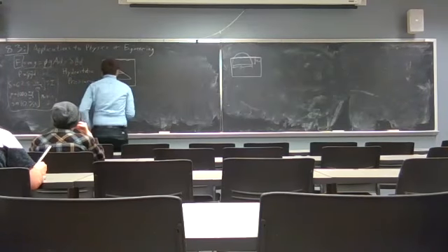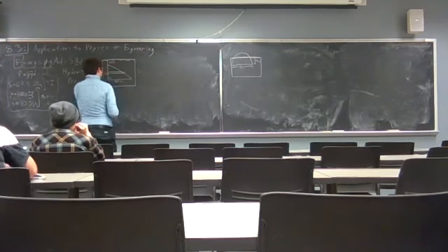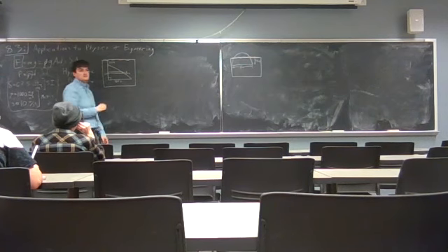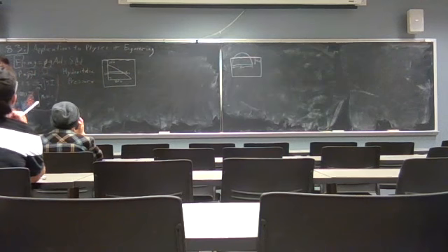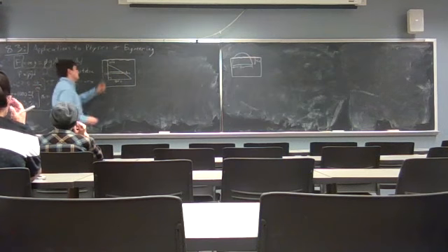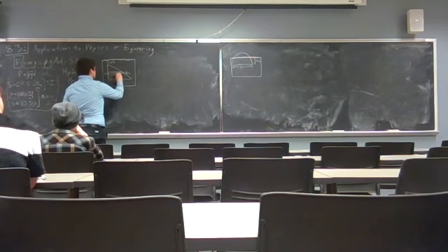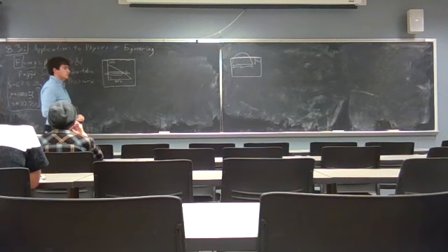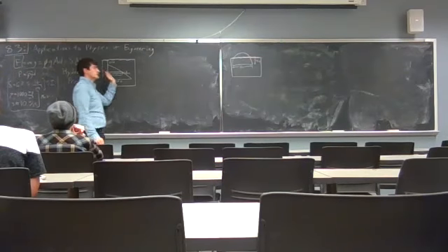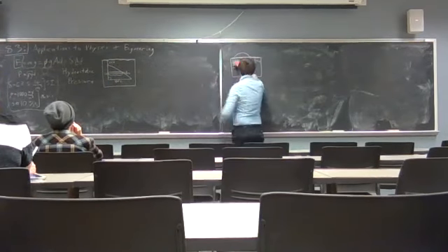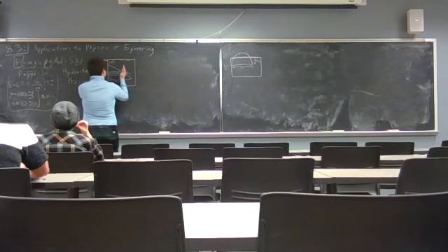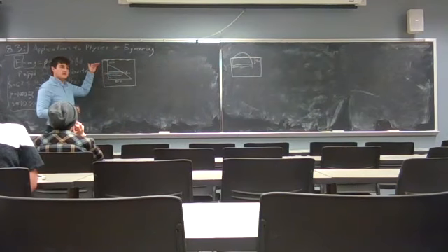When we add up all of these rectangles together, we're going to form the integral of it, right? Each of these rectangles is going to have a particular width, which is going to be our delta x in this case, right? So that's more broad. Obviously, when we go into the integral, it's going to be dx instead. But delta x is the width. So our goal in most of these problems is to figure out what the width is in each case, right? We need to figure out, depending on what the object is, here we have a triangle. Here we have half of a, this is supposed to be a semicircle. We need to understand how the length of this rectangle changes as we move up and down, okay?